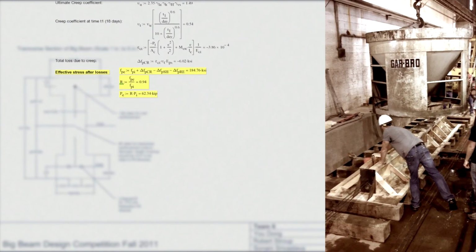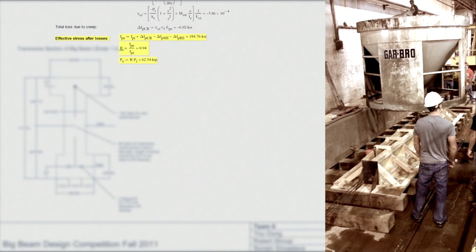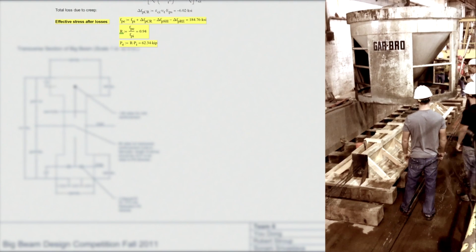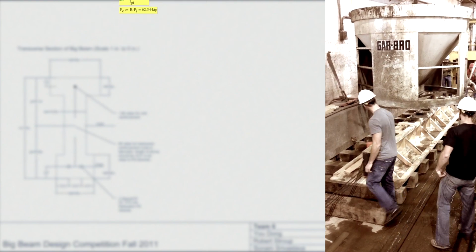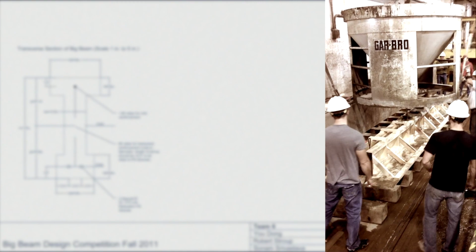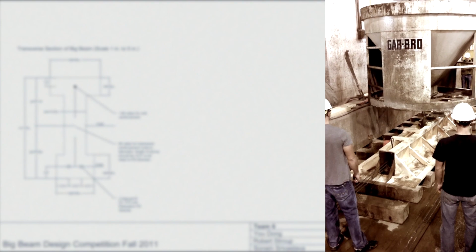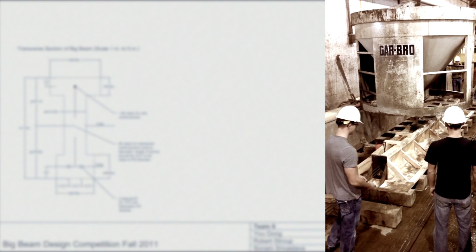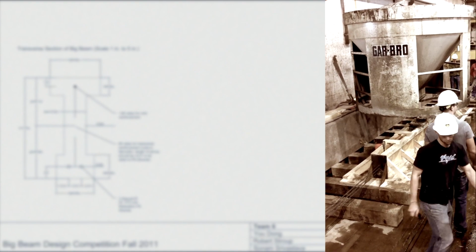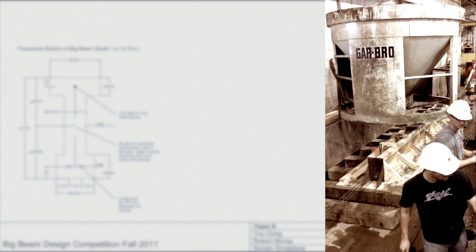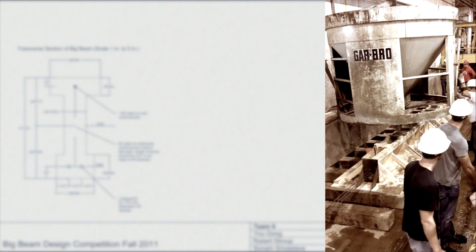By dividing the inertia by the area and taking the square root, we found the radius of gyration to be approximately 5.52 inches. Lastly, the sectional moduli were calculated at 310.63 cubic inches in the tension fiber and 285.69 cubic inches in the compression fiber. The demands on the beam included a self-weight of 85.22 pounds per foot, an induced moment of 2.73 kip-feet due to self-weight, and an additional induced moment of 60 kip-feet due to the live load.